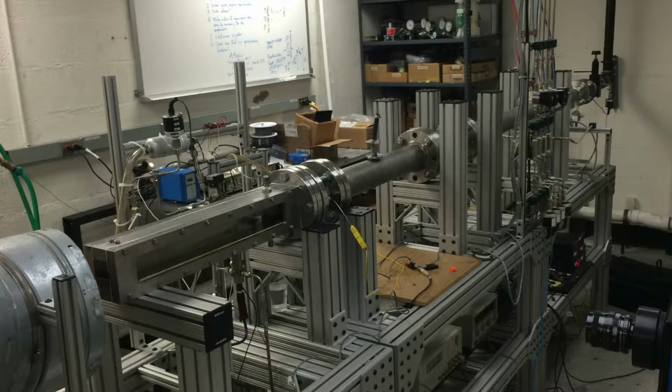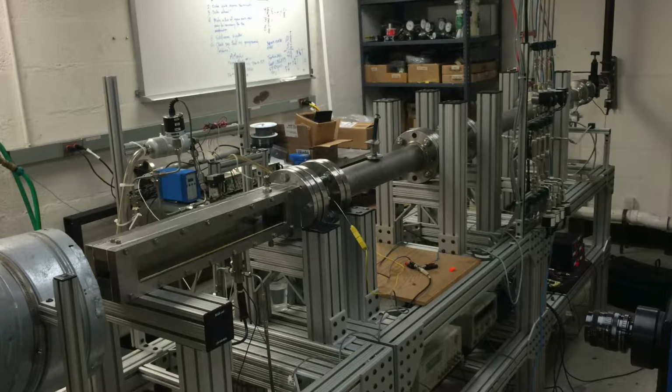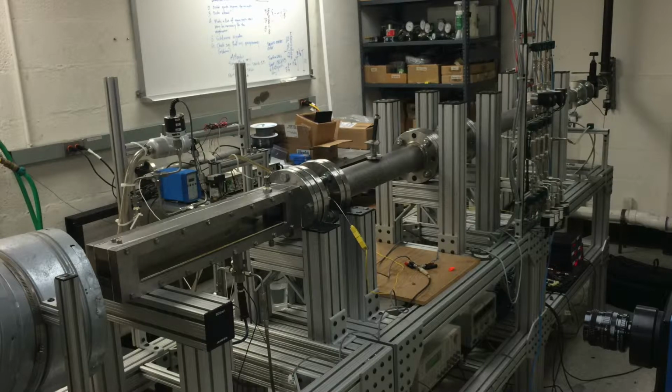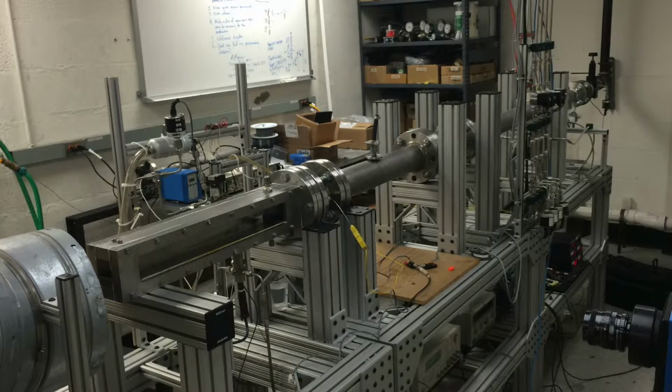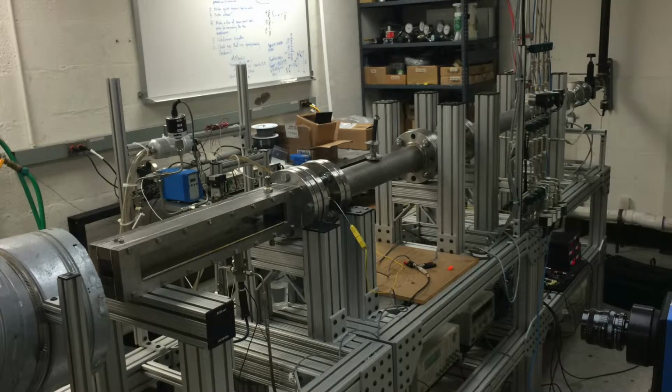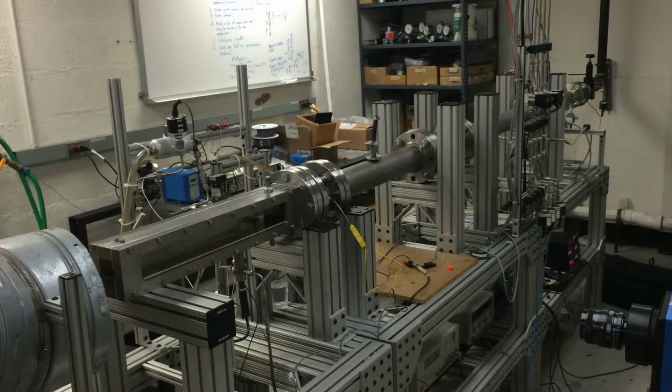Okay, so in order to increase the thrust of an aircraft gas turbine engine, an additional component called the afterburner is often used. This component allows additional fuel to be injected into the hot exhaust flowing out of the turbine, where it can combust and increase the enthalpy of the exhaust jet. This causes an increase in engine thrust.